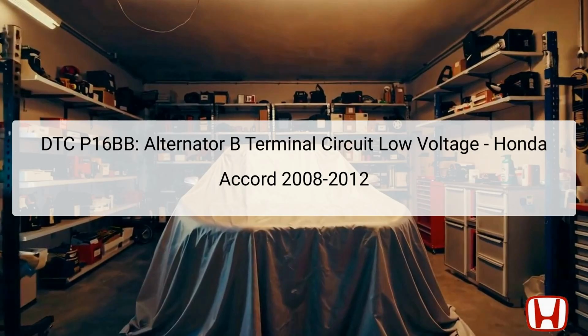Its location is generally found near the engine compartment on the driver's side, mounted to the engine block. The structural integrity of electrical connections is vital, as loose or corroded terminals can lead to inconsistent voltage readings, triggering this DTC. Before diving into troubleshooting, it is essential to gather all freeze frame data and snapshots for future reference. This information helps understand prior vehicle conditions that may have contributed to the fault.